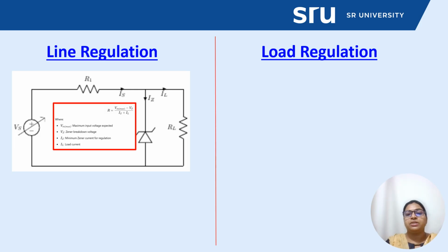It maintains a constant voltage Vz across the load as long as the input voltage is above Vz and within the design operating voltage, and a series resistance R, or here we have given as Ri, is to drop the excess voltage and limit current. So it basically